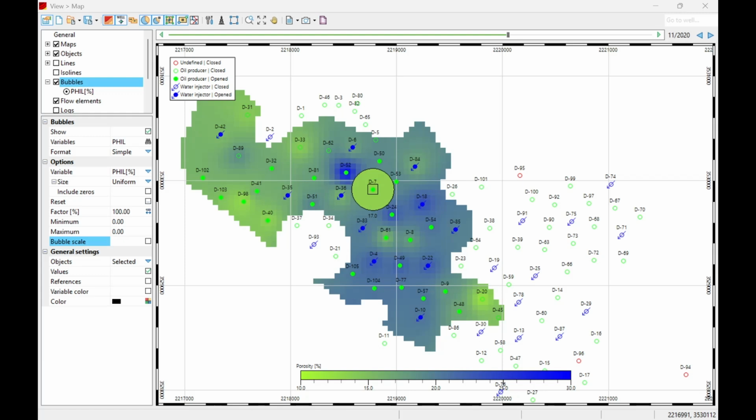We have used the petrophysical data window not only to show and to check the values that we created from another window, from the cross-section window, but we also use it, based on these values, to calculate new values, new information, that now we can use for other things. Maybe, for example, we can use it to create allocation factors or things like that. So the petrophysical data window is quite a potent tool that we can use to fill our information regarding, as I said, the petrophysical data of the wells and layers.